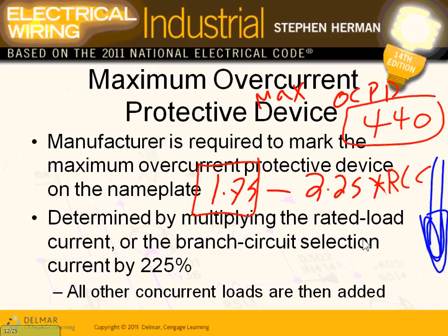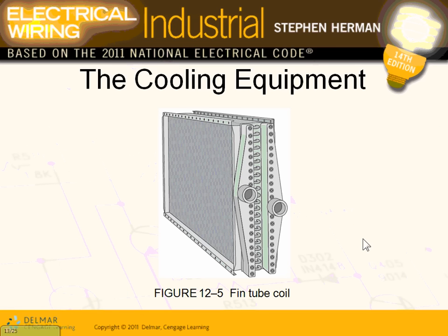And the other option is to custom design a fuse. And the third, more logical option is to go down to the next standard. Any question? We did the calculation on these. This is just a quick reminder of what you need to do. Always start with 1.75 unless you know.